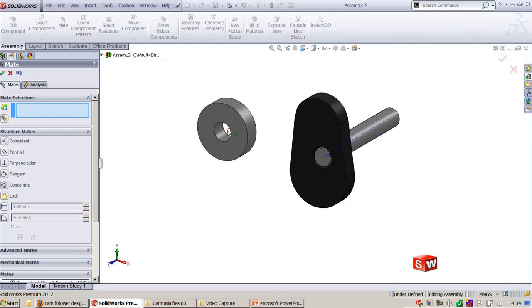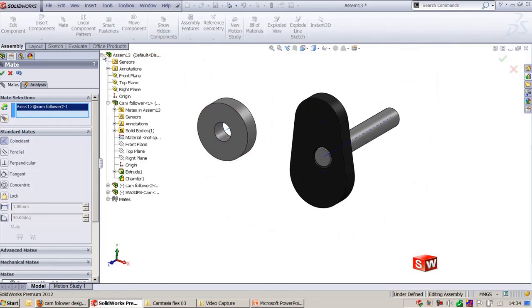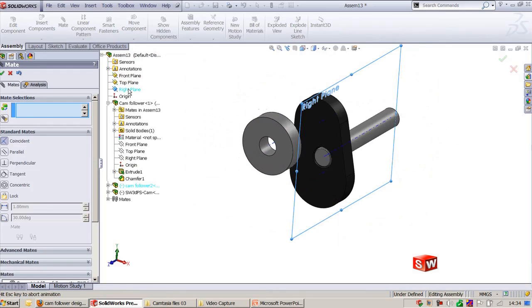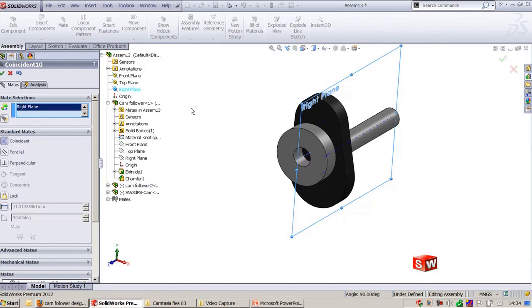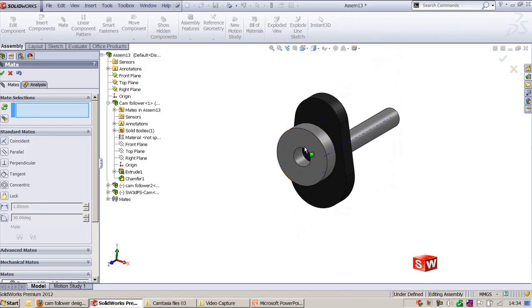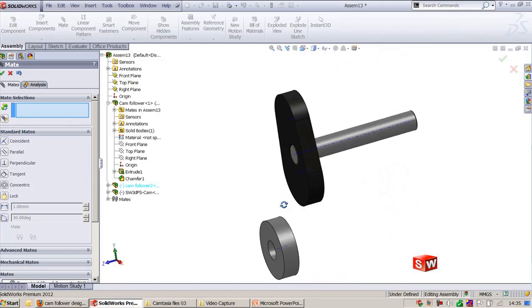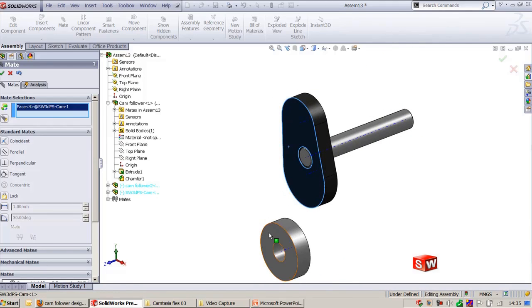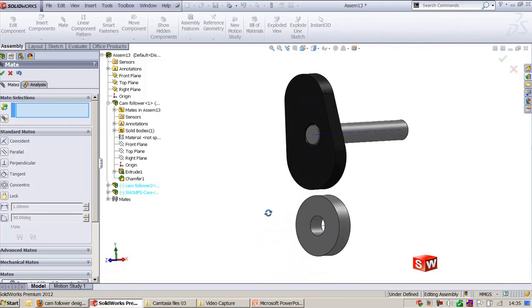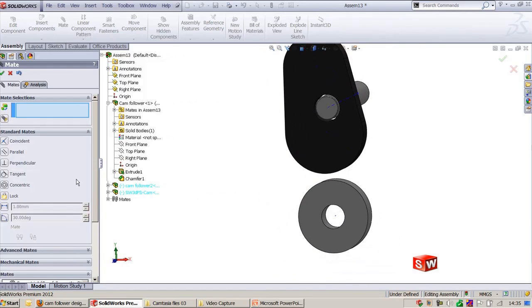And the next one is coincident this axis with the assembly plane. I will take this assembly plane. After this, I will drag this downwards, and once again I will say this axis should be parallel to this plane. And once I complete this, this face and this face should be coincident. And now at last I would like to go and apply mechanical mates.